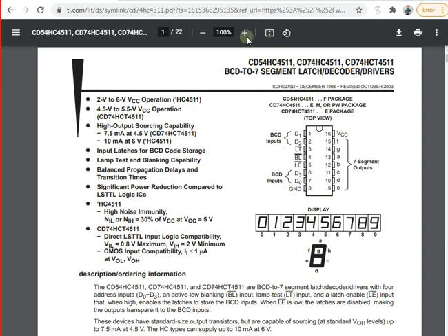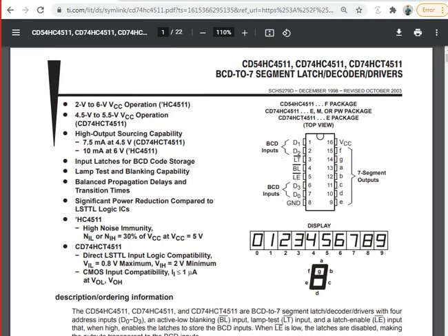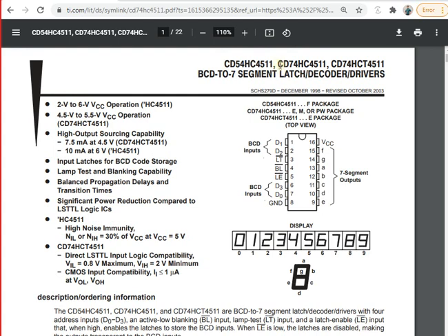As you can see over here, the first thing is you have to tally the name matches. That is 74. 74 is actually a series in which all the logic gates are, and you have done work on your logic gates in your FSc. So you already have an idea of how you are going to handle logic gates. If you want to find a NOT gate, OR gate, AND gate, you can find it. So 74 is the series number. HC is the speed. I'm not going to talk more on that one; in next classes you will talk about it in a little more detail.